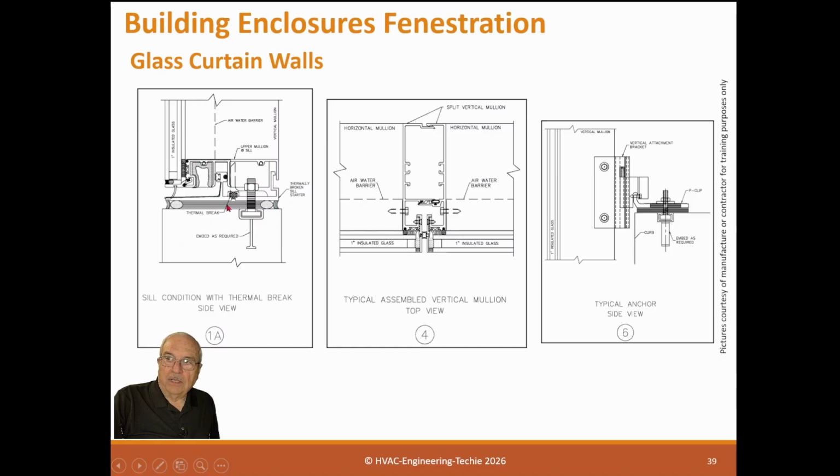The important thing about this is thermal breaks. And this one, I do not see a thermal break on it. You would think this is a thermal break, but actually it's not. It's a seal, because this is the frame right here, and it'll take temperature and transmit it right into the building.